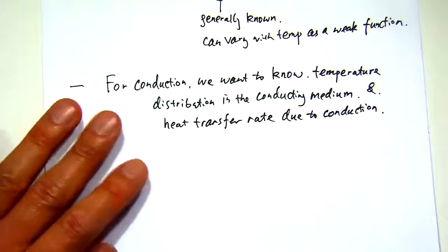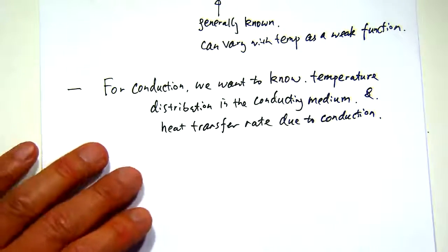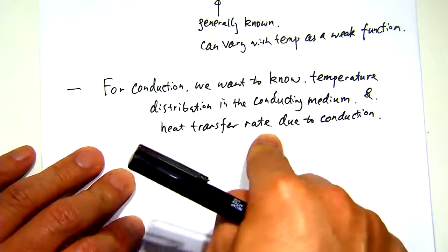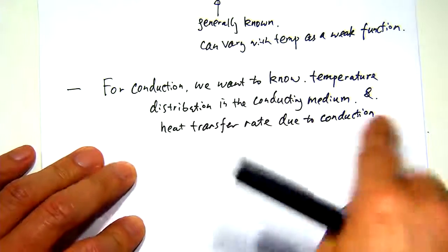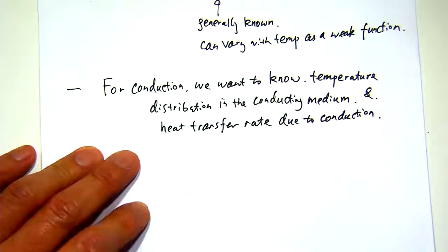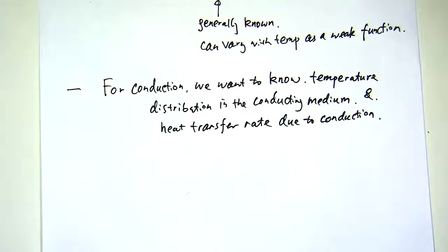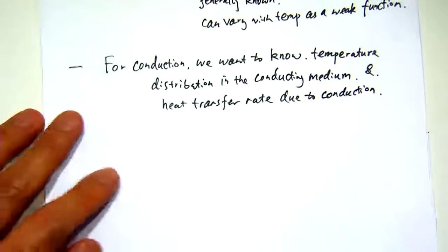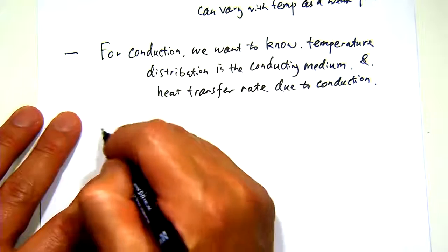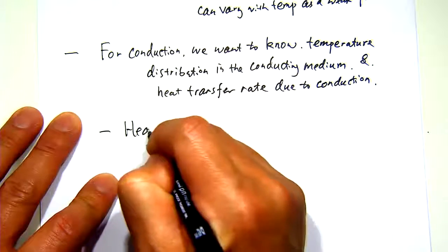For any type of heat transfer mode, we want to figure out what is the heat transfer rate. And particularly for the conduction problem, we want to know what's the temperature distribution within the medium. So that will require us to derive an equation called the heat conduction equation.